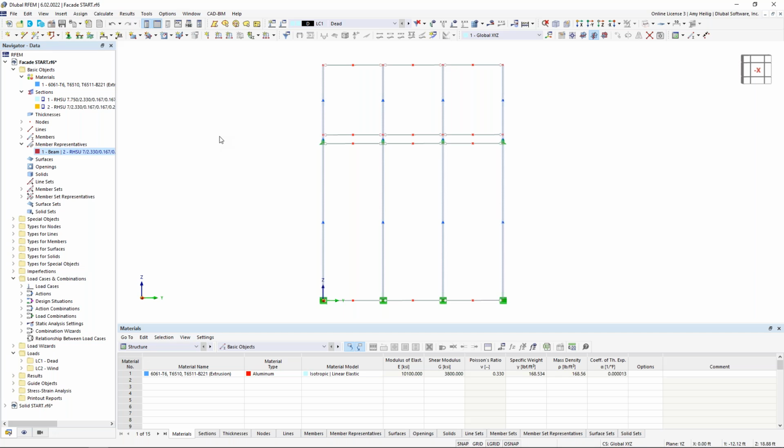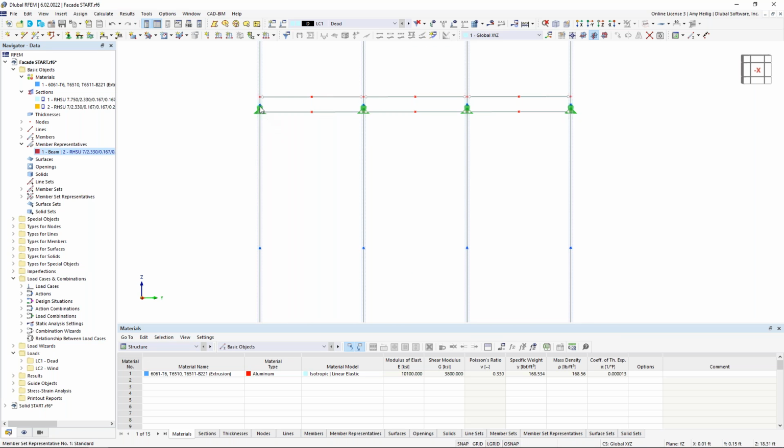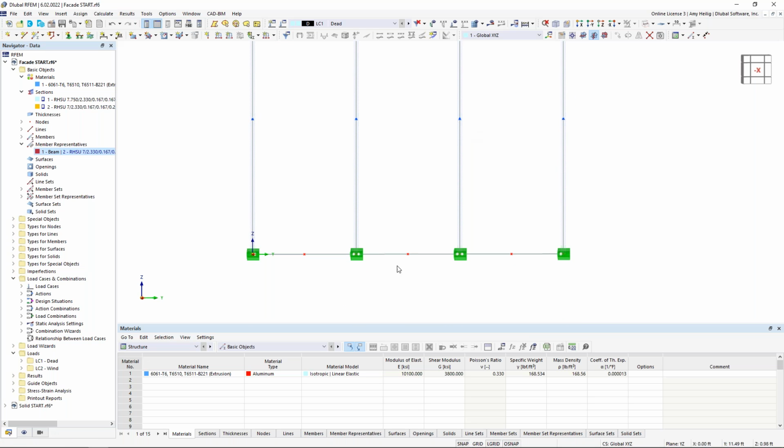And this will come into play later on with our stress design. I've also applied a couple of supports here. So you'll notice the nodal supports applied at the center line of these small segments. And then we have a sliding nodal support down here at the bottom.